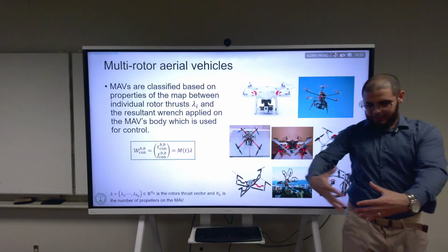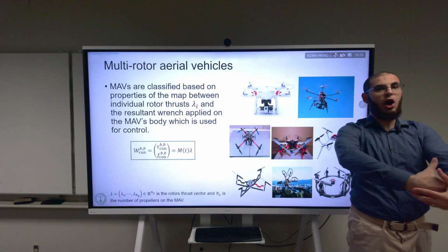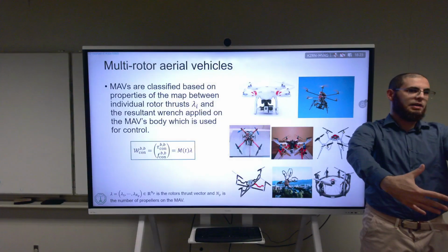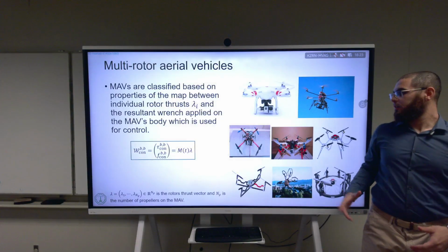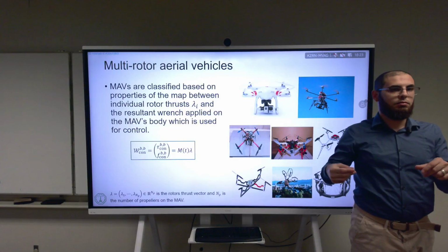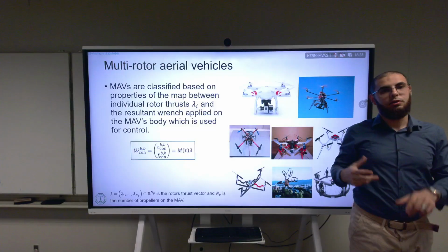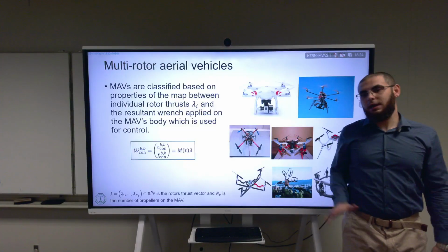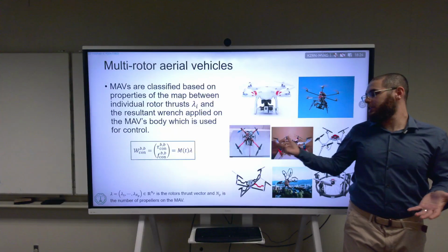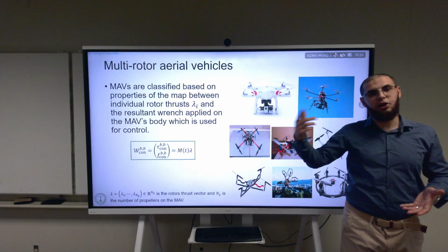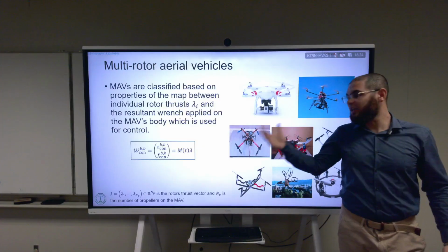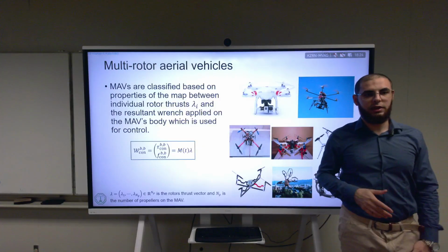At this scale of drones, the drones that you can just hug, all of these drones, they're huggable, as big as that, the propellers we use are very small, inertia-wise. If you just compare both, it's not worth taking their inertia into account. You can always think of them as a disturbance that the controller will take off, but not really model it as something that I need to take into account.